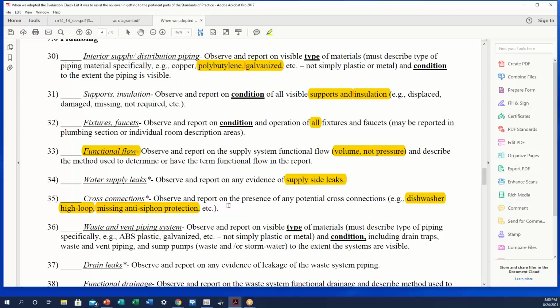So I don't know. What about the hose bib on the exterior? Does that have to have an anti-siphon on it as well? Yeah, we write those up all the time. So you need anti-siphon. Now, some of the hose bibs have it built in, and you know what it says on the hose bib stamped in the brass? It says built in. It's anti-siphon on it. It's supposed to resemble an arrow. Yes, it has an arrow on it.